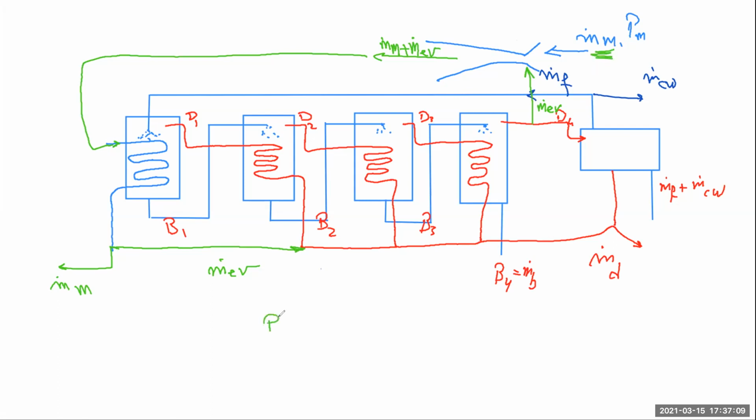So when we are talking about the performance ratio of this unit, then basically it's going to be m dot distillate divided by steam coming from the outer source, which is m dot motive steam. And then the equations which are related to the performance of the TVC, the thermovapor compressor, can be used as we did for the single effect evaporation. So we still have the compression ratio, which is basically PS over P entrained vapor.